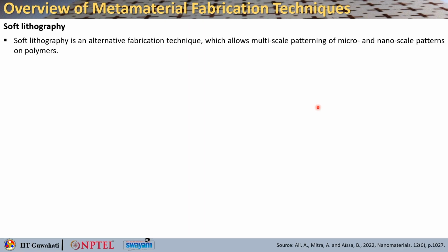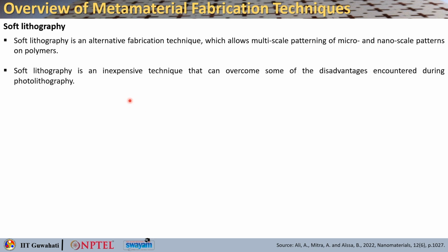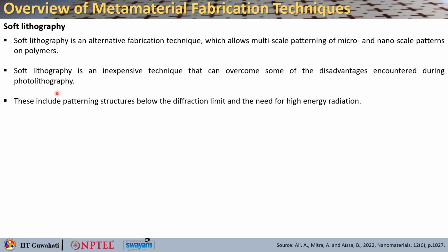And the last important technique in this particular fabrication method is soft lithography. It is also an alternative fabrication method which allows multi-scale patterning of micro and nanoscale patterns on polymers. Soft lithography is typically an inexpensive technique that can overcome some of the disadvantages that you have seen during photolithography.